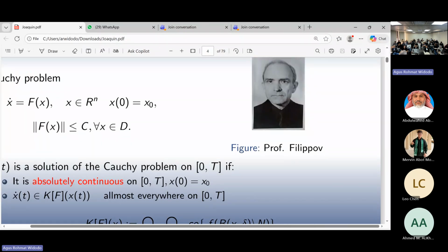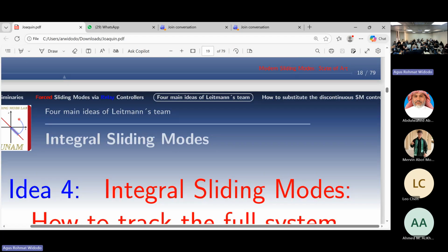Okay. What is sliding mode control? Imagine that you have your freezer and you wake up in there. What happens? You hear the compressor. What is the compressor doing? Switching on and off. Why? Because you have a corridor of temperature, and according to this corridor, your compressor switches on and off. So is the external temperature important? No. That's the point.